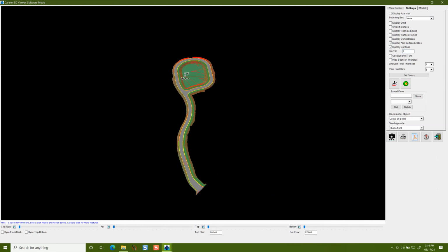You're right, I might even have to redo the whole thing. So here, this one is, see, there's that negative 0.258 starting here, and it stays that all the way up until it gets to that station, and it's got a 2% up. That's because that's coming across the intersection, climbing the pavement, you see.